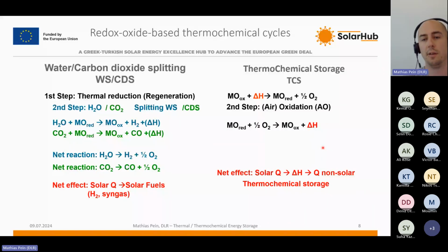And that concept is called thermochemical energy storage, where you have a chemical reaction adding to the storage capacity. But always keep in mind that these materials, being solids, naturally have a sensible fraction of heat storage, which is still the largest part of the storage capacity.